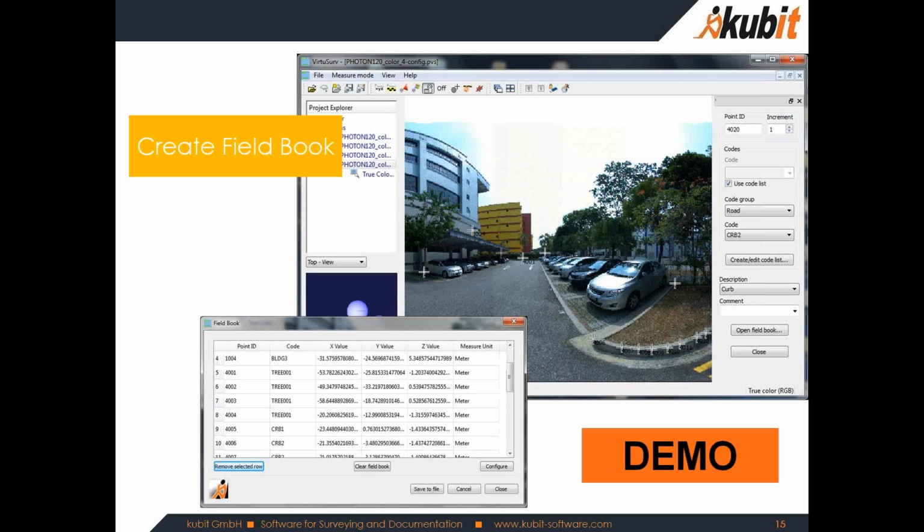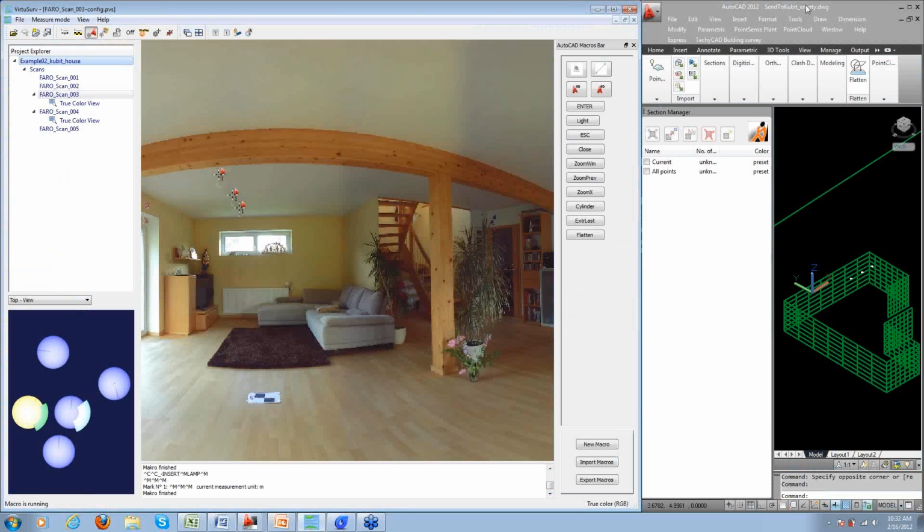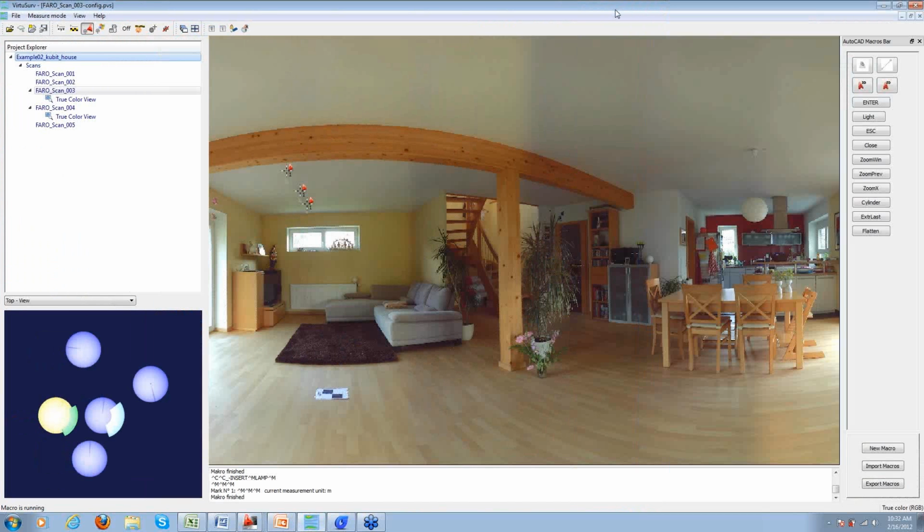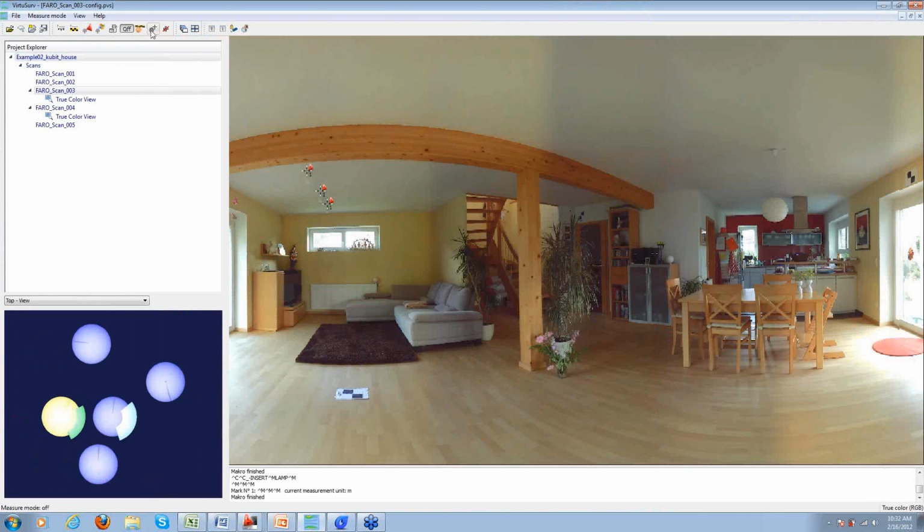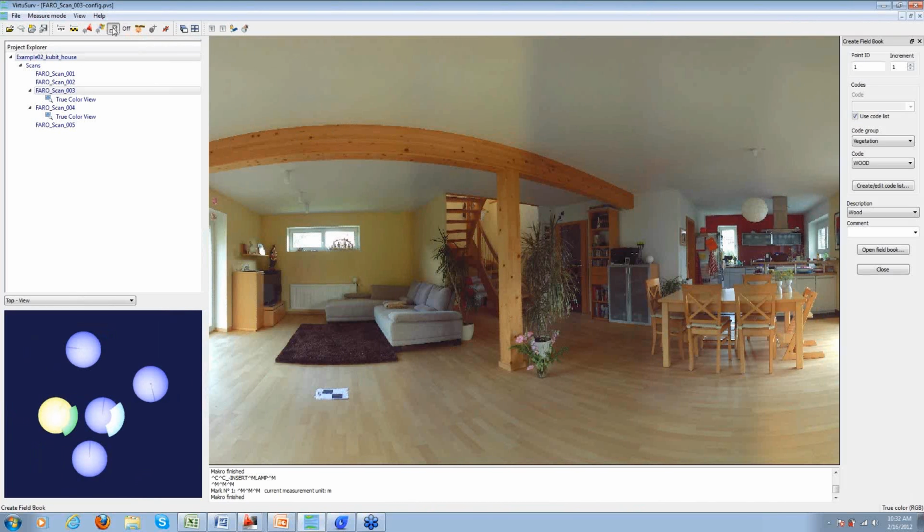And so here's just a quick screenshot, but we're going to show this for real. Let me just escape out of here. I don't need my AutoCAD up. So let me turn off my AutoCAD connection here and clear out all these lines. And I'm going to turn on the Activate Fieldbook option instead this time. And you can see that that brings up our Fieldbook interface.